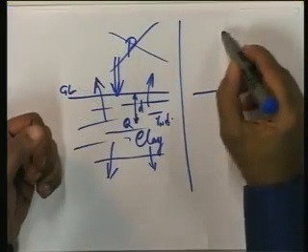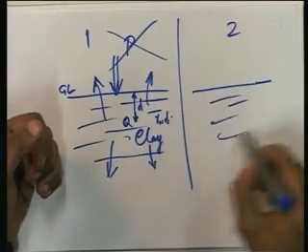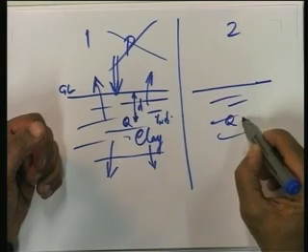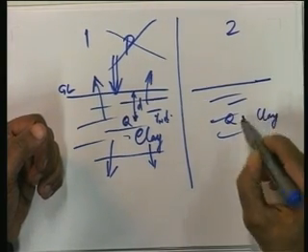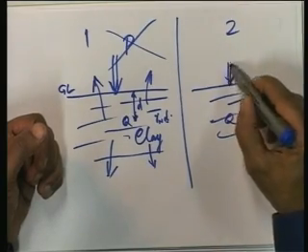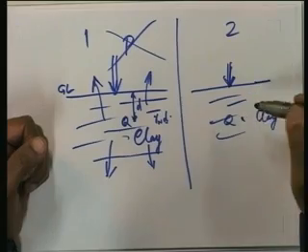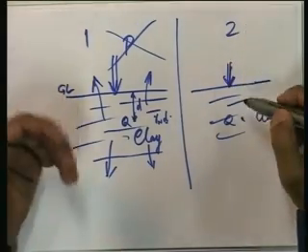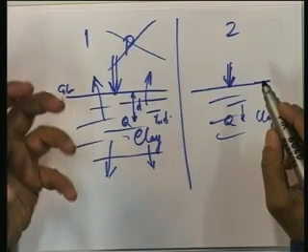So, if this is the second stage, this is the first stage, then now the water at any point inside the clay layer at the same depth is experiencing a load corresponding to what is applied here, and that load is in the form of an excess hydrostatic pressure.